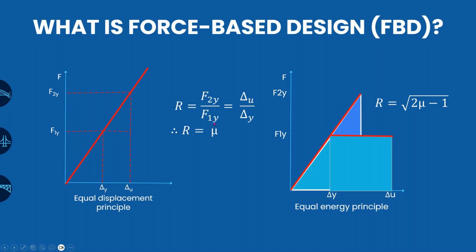Now this particular mu is basically the ductility, and depending upon past experiences, we have calculated the response reduction factor R by evaluating the structural performance under different scenarios.